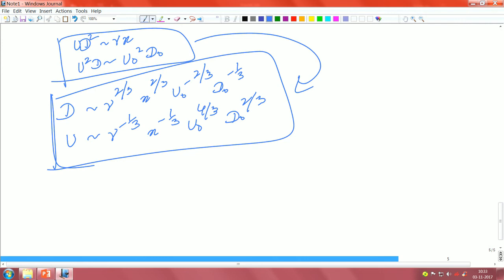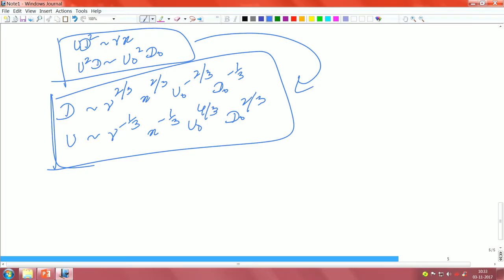First we did a simple scaling argument. Next we used the fact that the jet is bleeding out into a quiescent reservoir. As a result, far field quantities vanish. So the only thing remaining is that the initial momentum of the jet is a constant momentum source. Equating those two, we related u and d to u naught and d naught, and we found our crucial second expression. Now you can take this problem further, and also apply it to a temperature field.